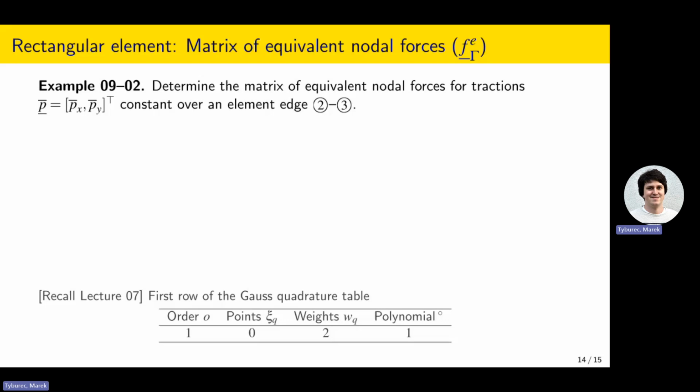Indeed, so it's T. Alright, so now we will integrate it on this different domain. So it's from -1 to 1. We modify this shape function matrix. It will be N^e, but now in these natural coordinates. So instead of Lx over 2, we'll have 1, because this one corresponds to 1 in this different system. And the other one, y, is the other coordinate, which is theta.